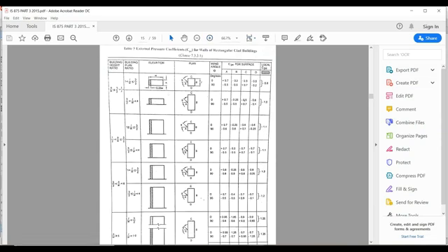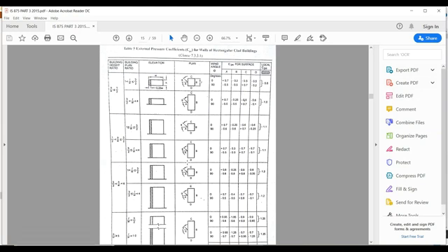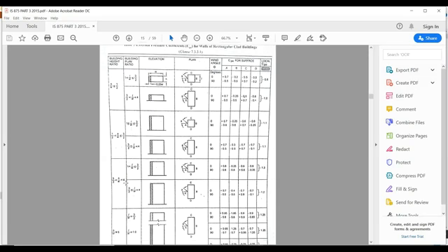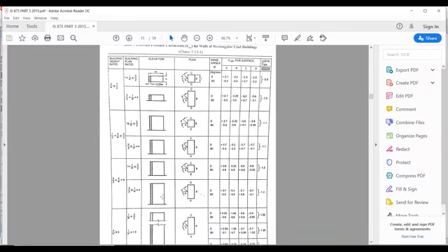As we have a height of 43 meters and a width of 3 spans of 4 meters, meaning 12 meters. So 12 meters width and 43 meters height, approximately 3 point something, which is between 3 by 2 to 6. And from 3 by 2 to 6, we have the length by width ratio. So the length is 4 spans of 4 meters, 16 meters. So 16 meters of length and width of 12. 16 by 12 is 1.33. 1.33 is between 1 and 1.5.